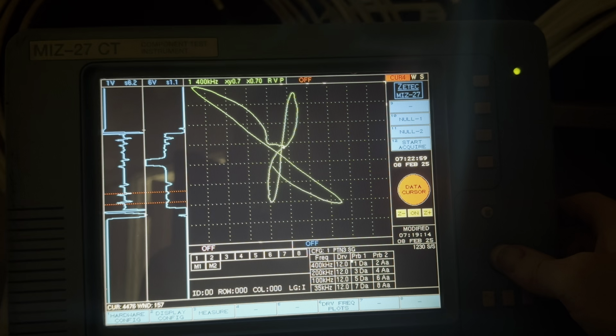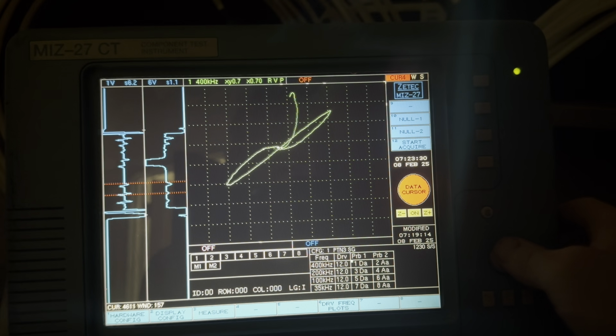Exactly how all that works, I don't know. Maybe even the best instrument designer couldn't tell you exactly how that all works, but we know there's a correlation between disturbed eddy currents at depth and the signals that are displayed. And when we compare those to metallurgical known defect measurements, we have figured out over time that, hey, these signals have some definite correlation to known metallurgical depth, and that's why eddy current testing is useful.